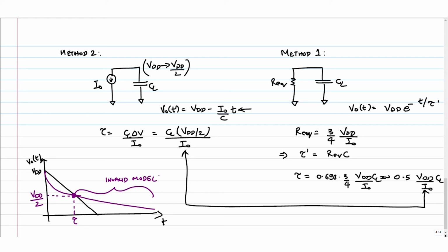The reason I am pointing this out is you will see that we use certain models in this course which are valid only in certain regions of operation. Outside that region of operation, if you ask me what the value of the model is, I would say I don't care, because the model is not even meant to handle that region of operation. That's the point I am trying to drive home here, okay? Any questions? The other thing is, of course, later when I start putting transistors in series or in parallel, then it's very easy for me to reduce that network using series parallel resistance combinations if I know R equivalent. With the current source model, I cannot do that, okay? Any questions here?